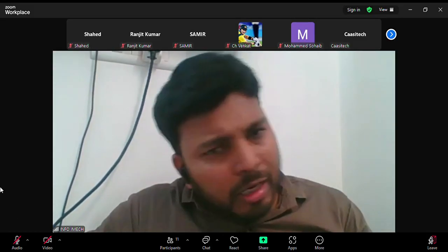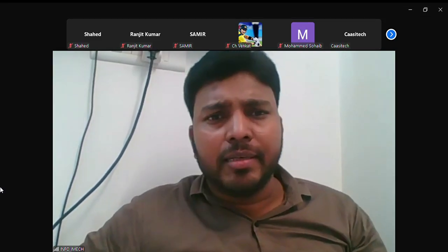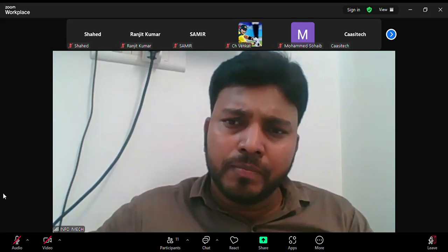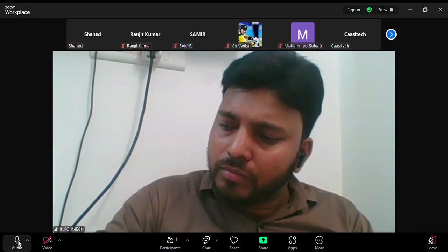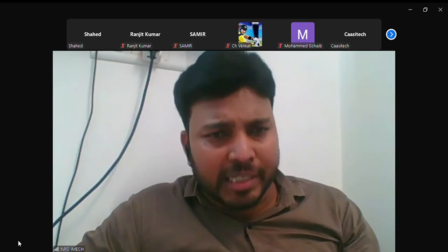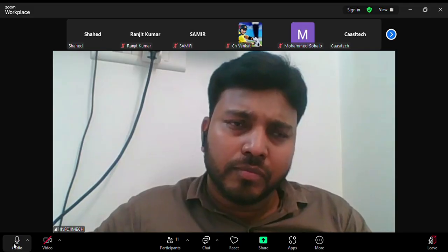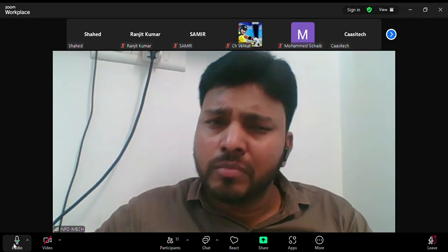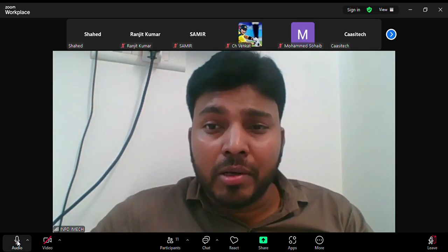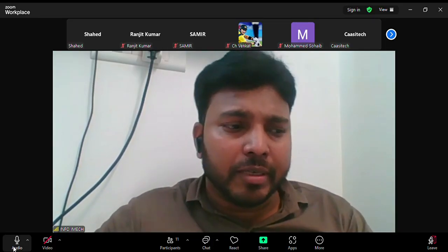Okay, so now there are two questions, guys. I'm repeating the questions again. There are three main cases. What is the back wall echo? The echo from the thickness of the job, the total thickness. When will the back wall echo come? When there is no defect.